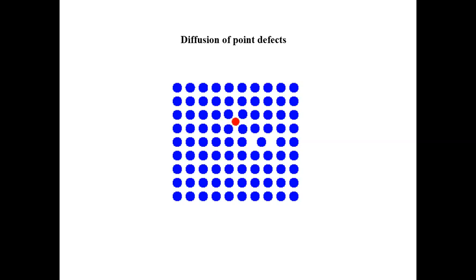Right? So this is quite useful because in phase transformation, we want these solutes. You can imagine that these red interstitials are solutes, like carbon in a steel, right? They can move around in the system so that at a given temperature and proper conditions, you can induce different types of phases due to the diffusion of these guys. Okay, so that's basically a schematic picture for solid state diffusion.